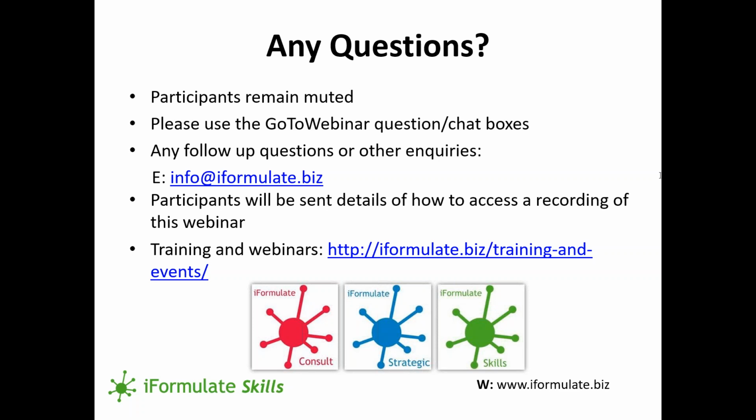Can we make particles of uniform shape using fluidized bed drying, David? No. You can't take an oval particle and make it into a sphere. You can actually, so a lot depends on the shape of the starting material. If you are willing to agglomerate, then you can build up agglomerate particles of a similar shape and size. Yes, you can do that, but it's difficult if you've got a non-spherical particle and a range of different particles in the fluidized bed to make them all the same. The only way of making them the same is to build them up to an agglomerate which has similar shapes and sizes.